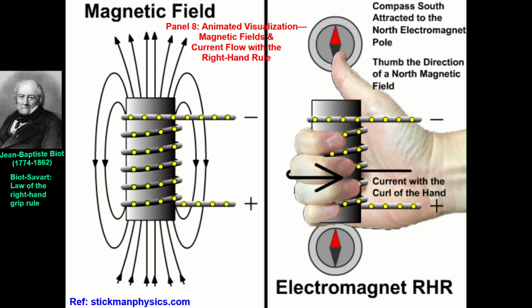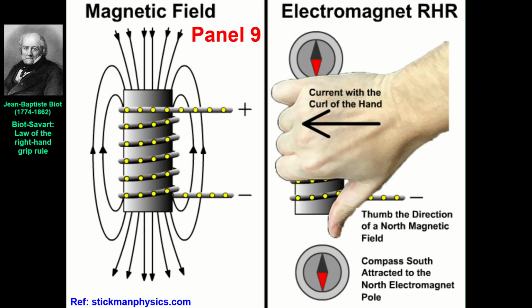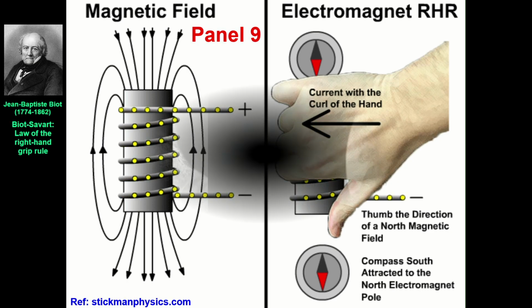To understand excitation and ionization, let's review magnetic field generation. An electric current flowing through a coil produces circular magnetic fields. When loops stack, their fields combine into a concentrated central field, like a bar magnet. The right-hand rule helps determine field direction. Curl your fingers with the current and your thumb points along the coil's magnetic field, following Biot-Savart and Ampère's laws.